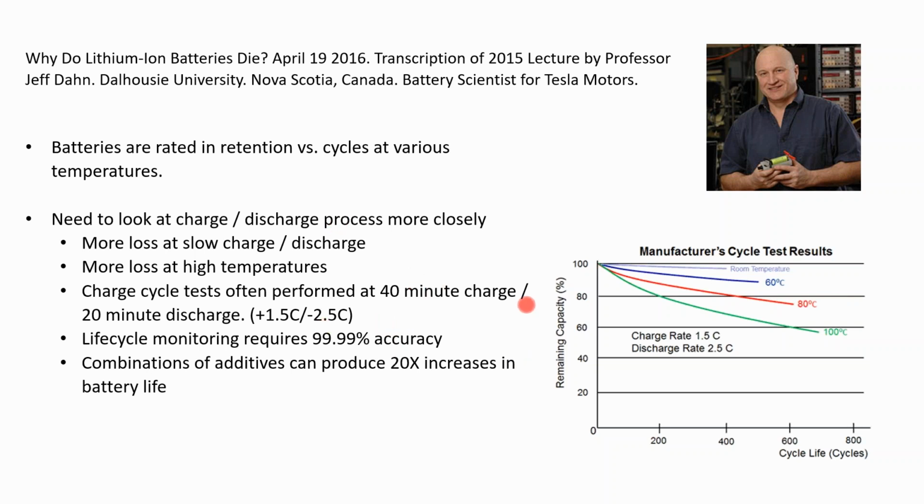Lithium-ion batteries are more efficient. You can charge and discharge them more rapidly. And then what he's saying is that for the same amount of power, the quicker the charge and discharge process, the less buildup you have on that anode. And so a lithium-ion battery that can be charged and discharged more quickly than, say, lead acid is going to have a longer life out of it.